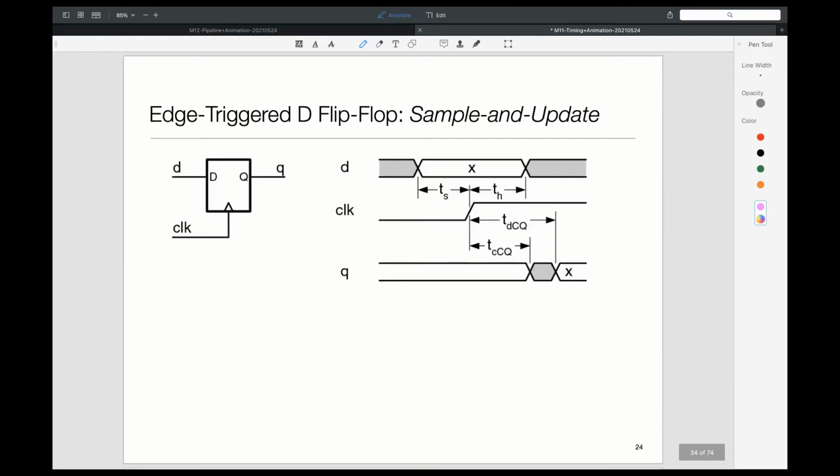At the clock edge, because the input D had a value X, after some time output Q will see the value X. And remember, we also talked about how before Q changes from its old value to the new value, it may jump up and down, or if it's a multi-bit value, it may go through some intermediate values. So that's why you see this stuff out here.